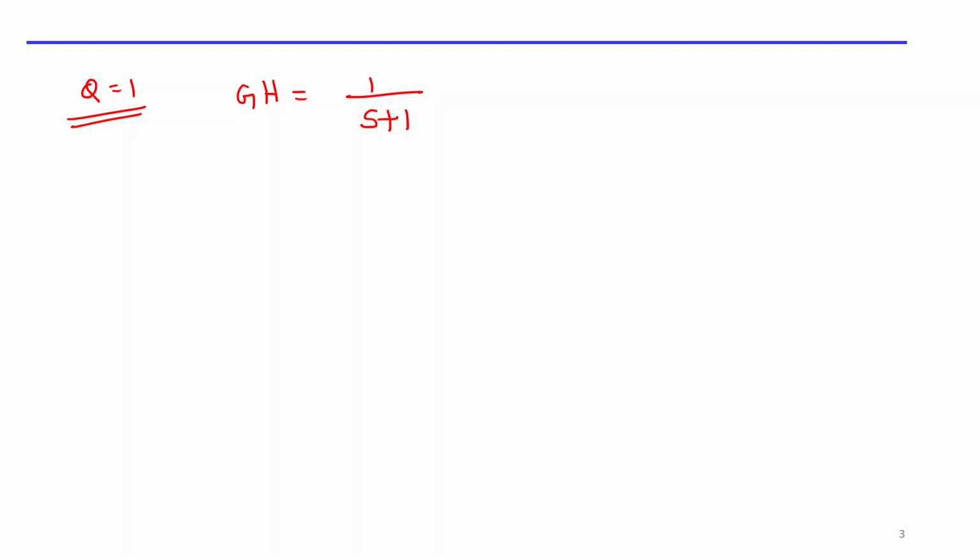Then you have to do the RH criterion and find out the system stability. You have to check where the poles are located, and you can comment on that. But if you use frequency domain analysis, then without doing the closed loop system analysis, by only analyzing the open loop system, we can tell the closed loop system stability. I'll tell you how to do that.